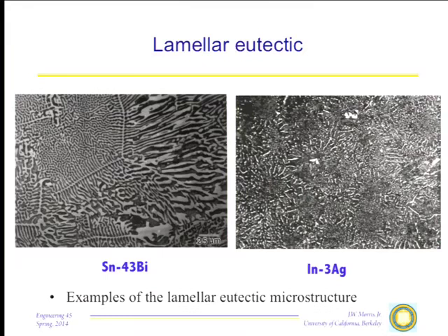The problem you run into with any of these things are the uncontrollable features, the thermal noise of the system. Maybe you bump the container while these things are growing. You get something that looks like this as a consequence. Those are the things that are hard to model. As I said, there are a couple of applications where it would be really nice to grow a perfect eutectic. So it's not easy to do, and we'll talk about that later, of course.